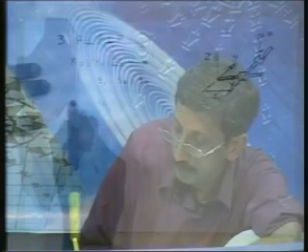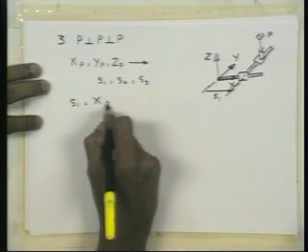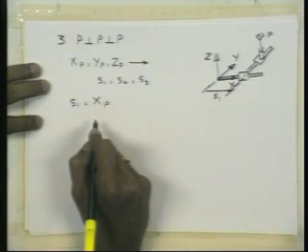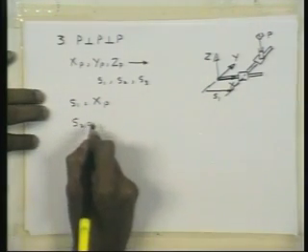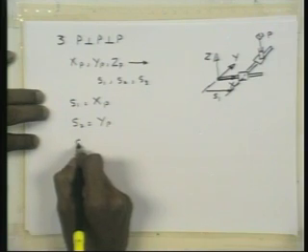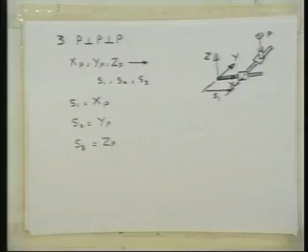So the question is, what are the values of S1? Fairly straightforward. This is xp itself, correct? If I define the joint positions like that, S2 is yp and S3 is zp. Why did this simplification occur? Because I oriented the global reference frame axes along these convenient directions. So the whole problem was very simple to solve.